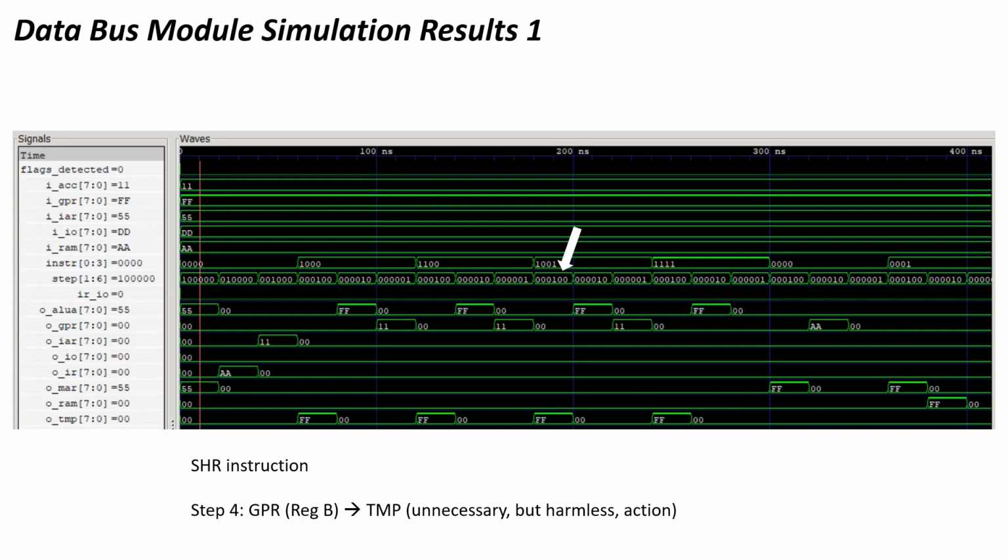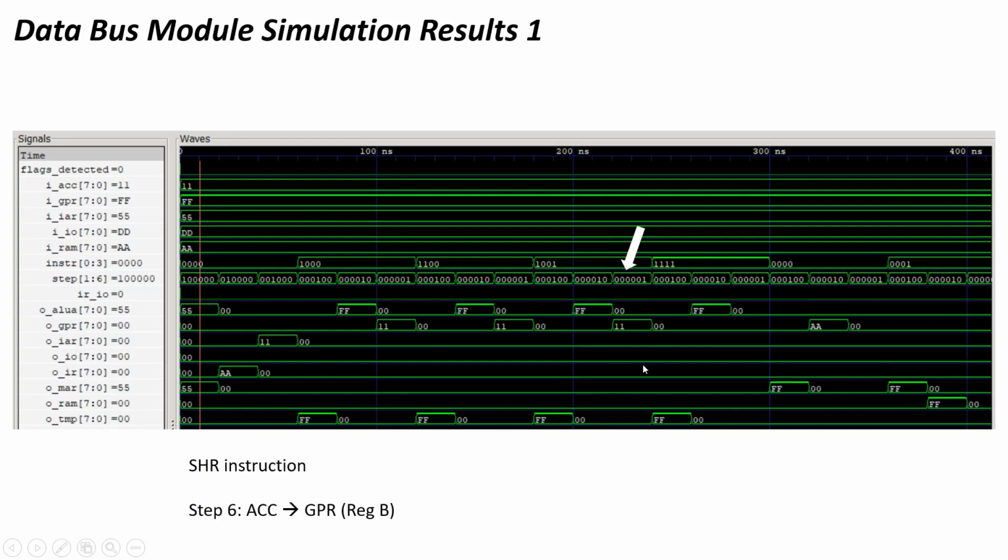The shift right instruction, which, remember, these control signals are still activated, although this is a one operand instruction. It doesn't hurt or do anything that register B is being used, because when it comes to the actual operation, the ALU will only look at the value at ALUA for register A, and then we'll put that back into register B. The compare operation does two things, and then it compares, right? It loads from register B, then register A, and then it sets flags. So there's no step 6 operation. Okay, that's all the ALU instructions I wanted to cover.